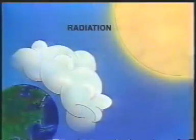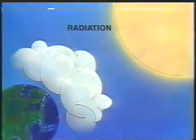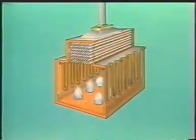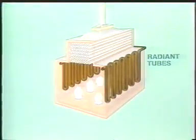Radiation is the means by which heat is transferred from the sun to earth. Radiant heat travels in waves, as light does. For this type of heat transfer to occur, the object being heated must be in direct line of sight with the source of heat. As with visible light, these radiant heat waves can be reflected. In a furnace, the tubes that are exposed to direct heat from the burners are called the radiant tubes. Heat is transferred to these tubes primarily by radiation.